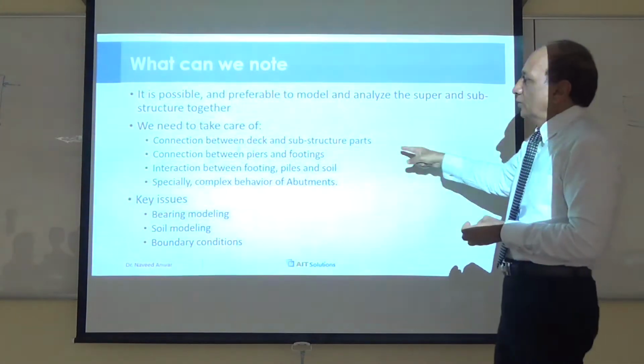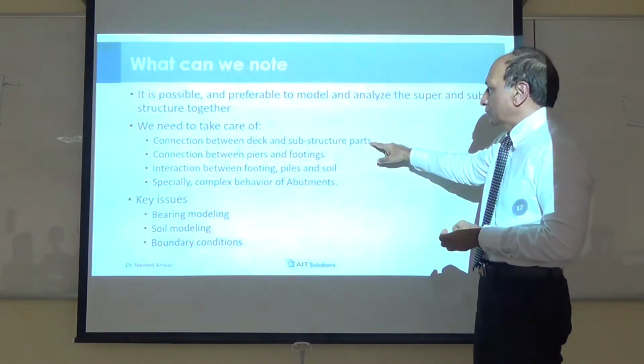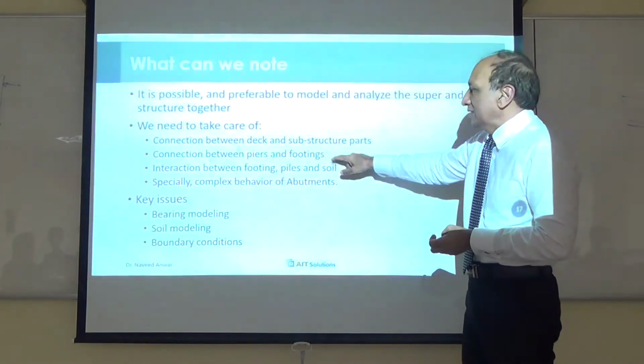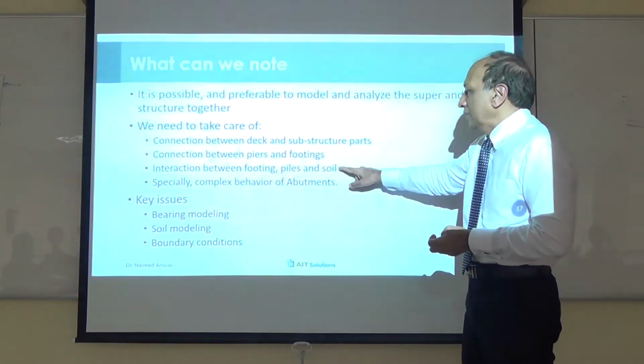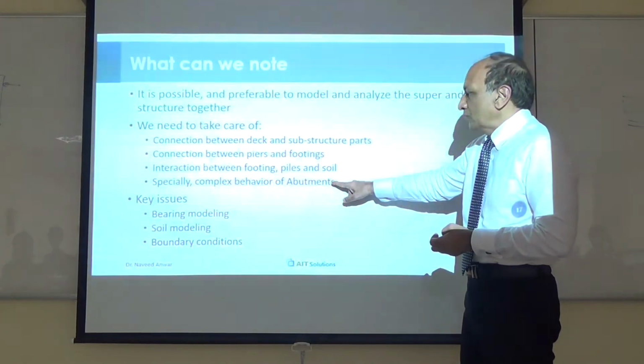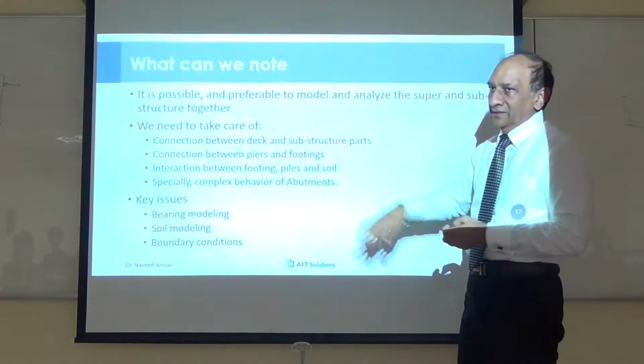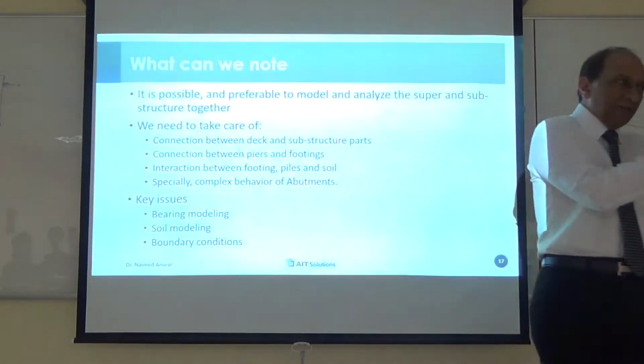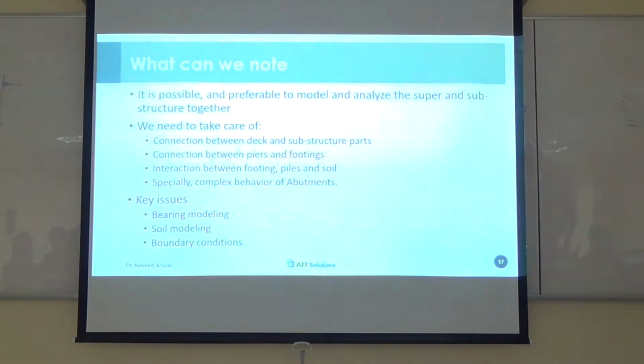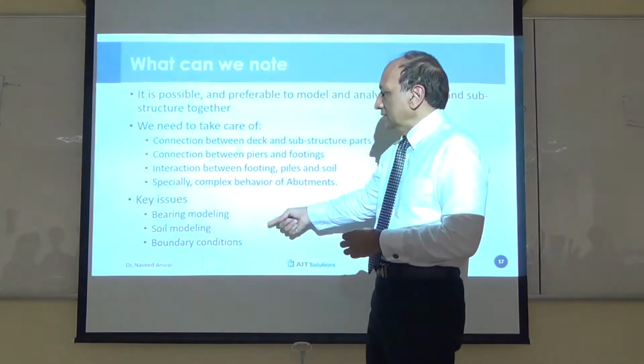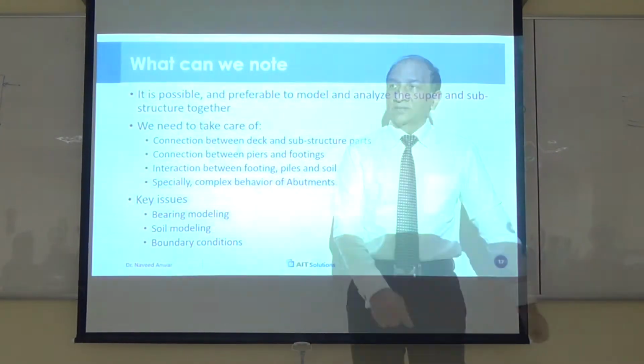We need to take care of the connection between deck and substructure parts, connection between piers and footings, interaction between footing, piles and soil, especially complex behavior at the abutments. So when we go to abutments, the end of the bridge, it becomes even more complicated. So key issues are bearing modeling, soil modeling and boundary conditions, right?